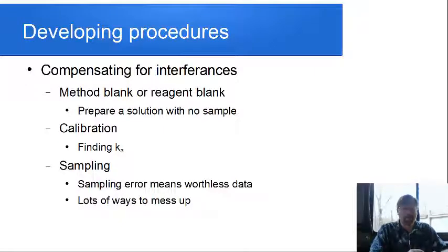And the vendor said, yeah, but the sample wasn't preserved at all, so of course it grew stuff in transit. So basically, they wasted the money to ship it, they wasted the money on the test, and it didn't tell them anything, because the data wasn't worth anything when it came in. So in terms of sampling, what you sample, where you sample, how you preserve the sample, all of that is very important and can have a huge impact on whether or not your data even means anything, as well as how accurate your data is.